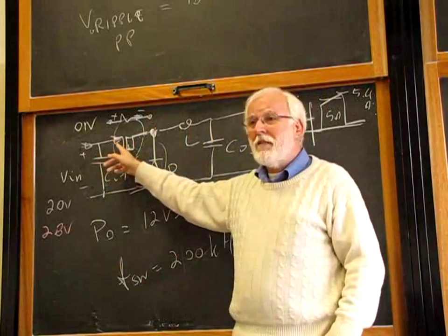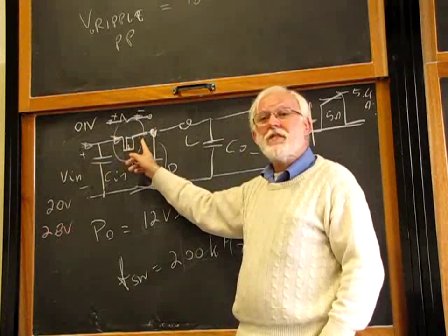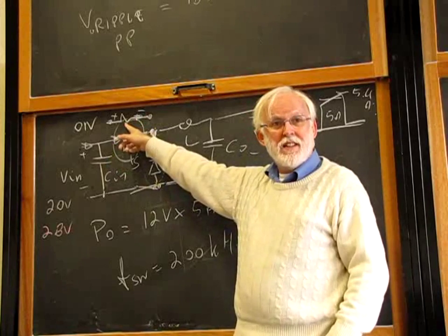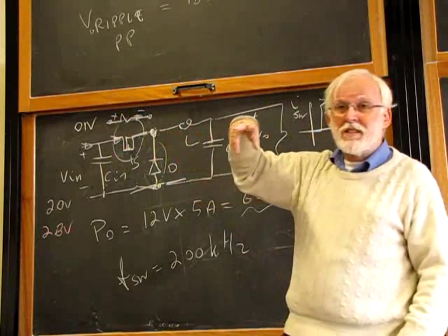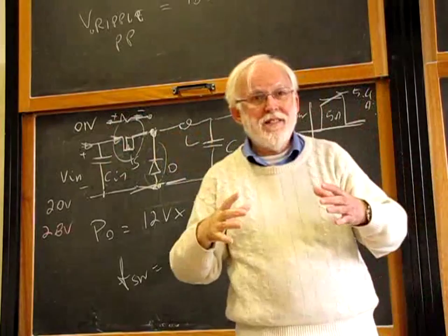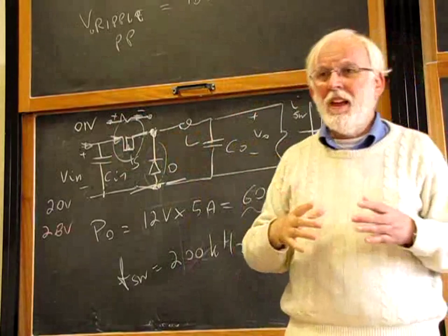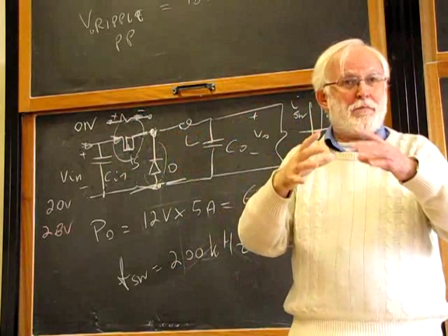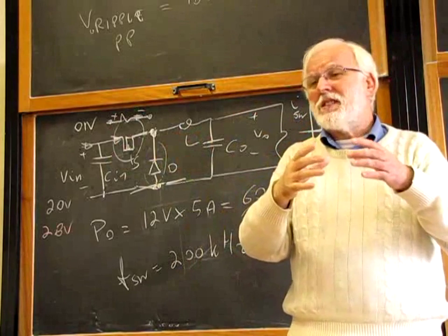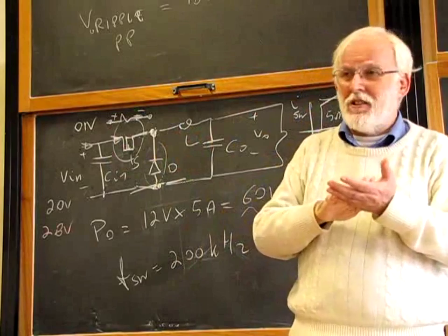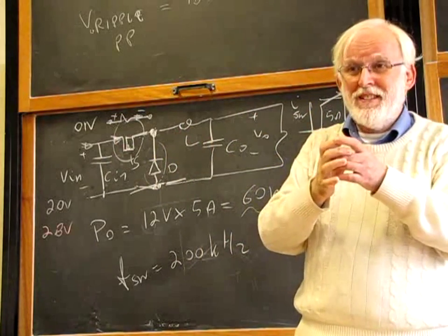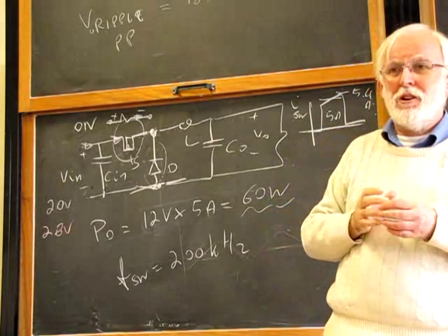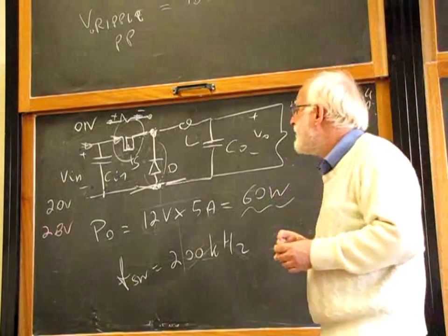But if you take a very large transistor, a transistor that has a very small RDS on resistance, you have two disadvantages. First, you need a lot of silicon. A lot of silicon area requires a larger package, and package is cost. Cost is not given directly by the silicon, it's given mostly by the package. The larger the package, the more expensive is your component, with some exceptions.